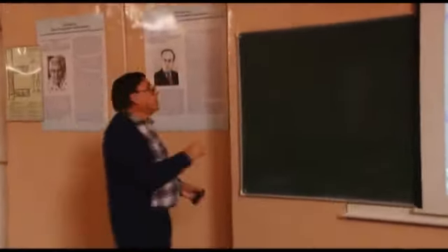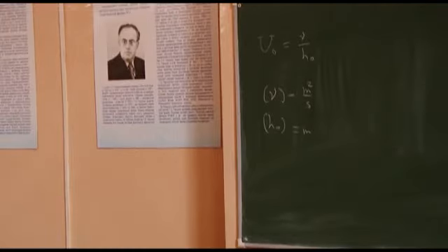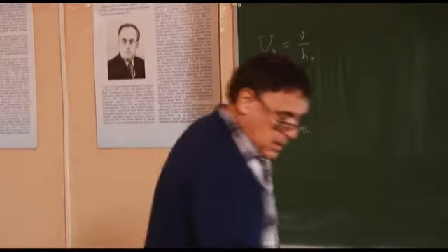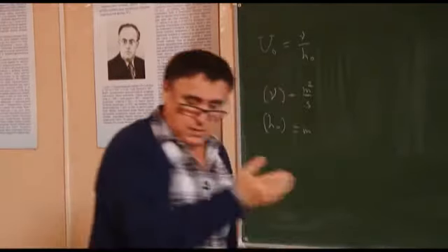Nu has units of meters squared per second, and H0, of course, is the mean thickness of the film, in meters. So if you plug it in here, you have units of velocity, and this is what's called the typical viscous velocity in the film or in the fluid system. Here we don't need to specify this U0, but if we need to make a decision, this is definitely one of the good candidates.